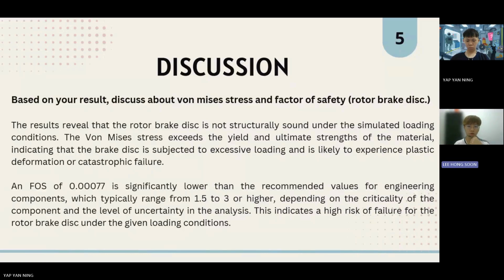The safety factor of 0.00077 is significantly lower than the recommended value for engineering components, which typically ranges from 1.5 to 3 or higher, depending on the criticality of the component and the level of uncertainty in the analysis. This indicates a high risk of failure for the rotor brake disc under the given loading condition.